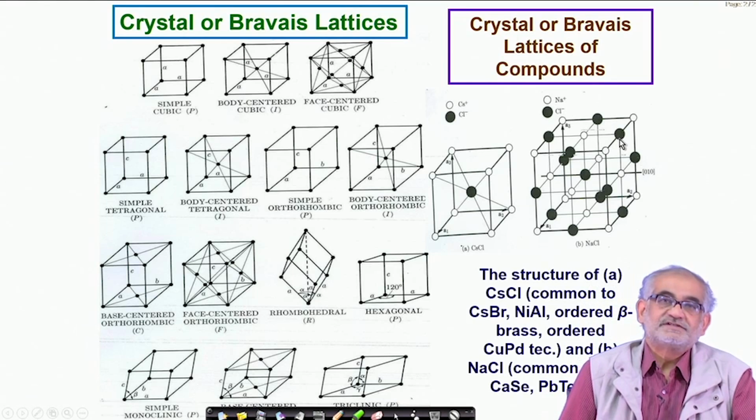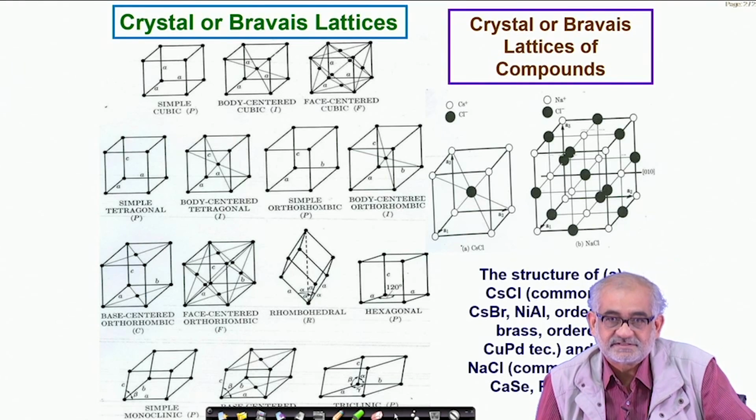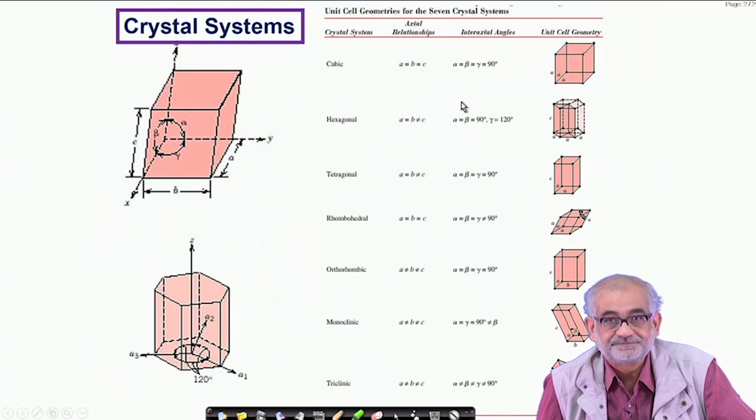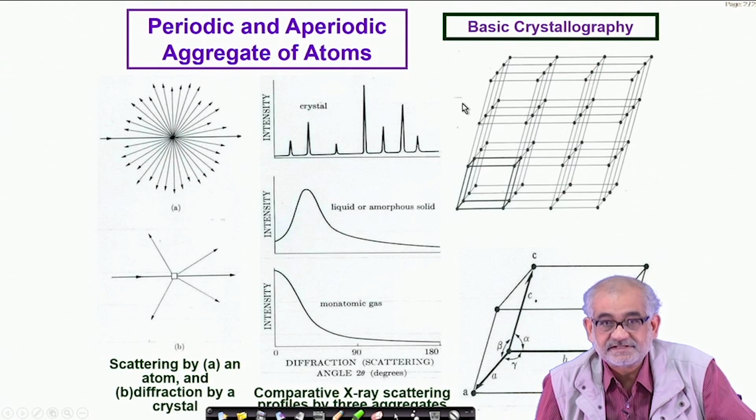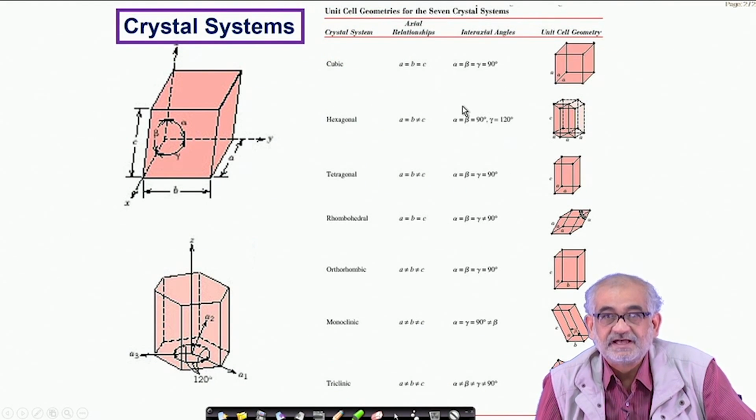The reason why I took time to explain these things, which are possibly known to you already, is that we must be able to distinguish between the structural hierarchy starting from point lattices or space lattices to unit cell, then lattice parameters of the unit cell, variation of which give us the 7 crystal systems, which are essentially primitive in nature, having atoms only at the corners.